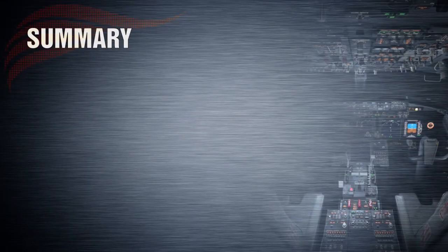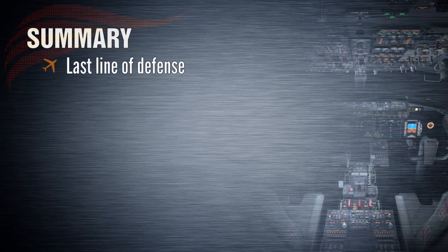We'll finish up as always with the lesson summary. TCAS is the last line of defense against a mid-air collision. It is completely independent of ground-based air traffic control. This is both a strength and a weakness. TCAS does not facilitate automatic reporting of resolution advisories to ATC.